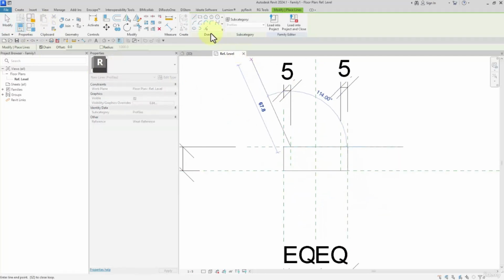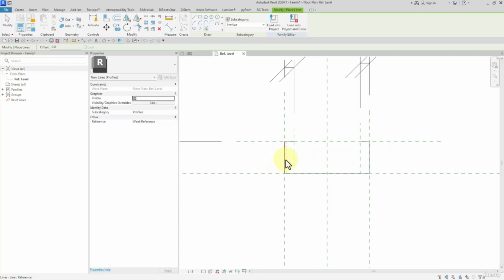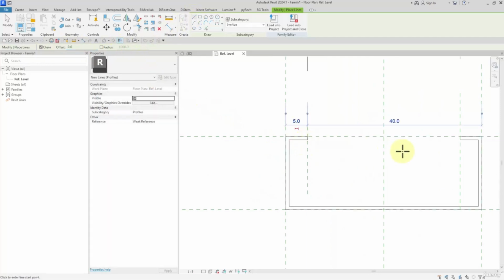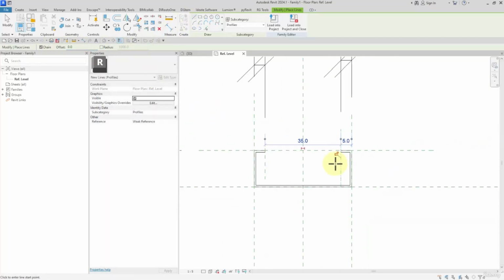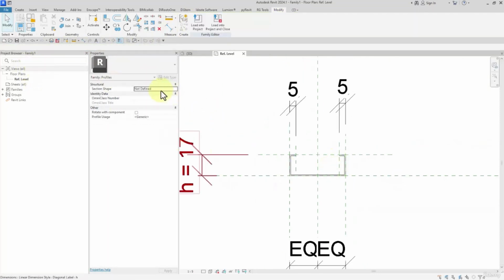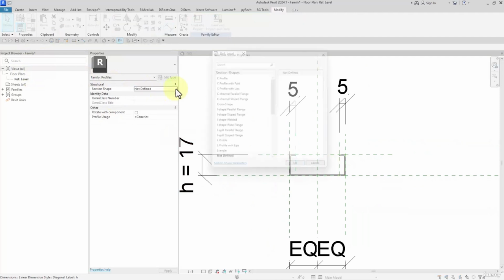Check it out. And then I define the offset, 8 millimeters, not 0.8. Then I hold down the cursor of the mouse, press down Tab to select the boundaries, offset 0. I enclose them. Well done.